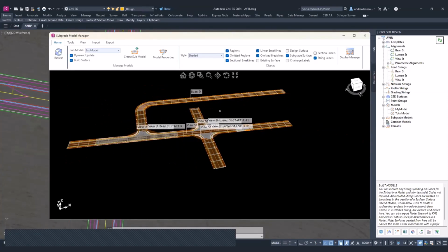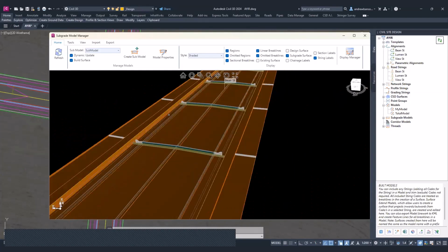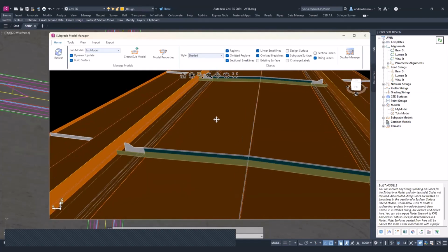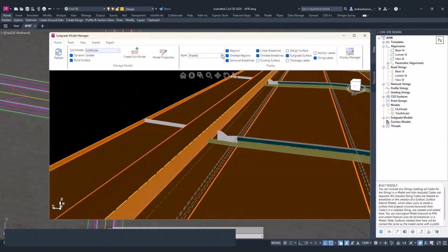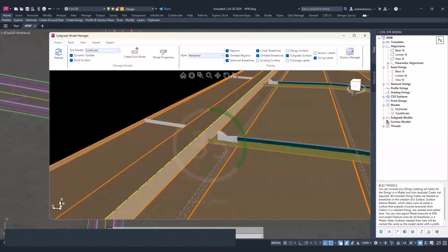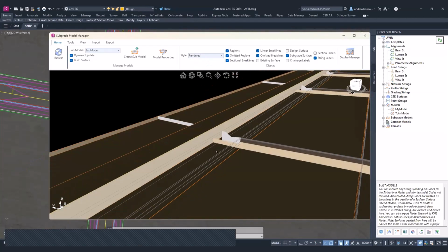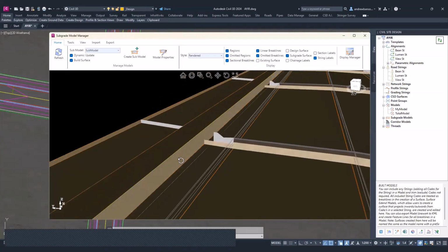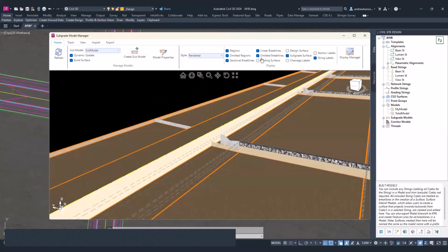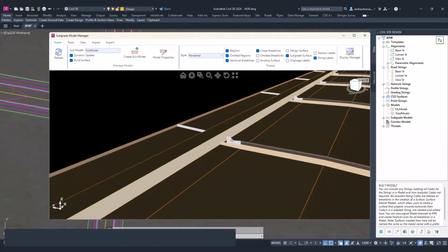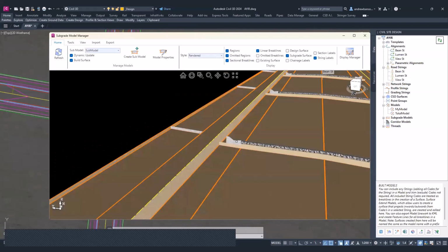And so what it does is, in a 3D environment, it shows all of your cross sections, and the orange surface here is that sub model that we could export out, or we could just export out the strings. The strings are what we're interested in, the orange strings here. Okay, and this is a full editor where you can go to a lot of detail in building the sub base exactly how you want, but still referencing your model builder or total model design, which represents the finished surface level.